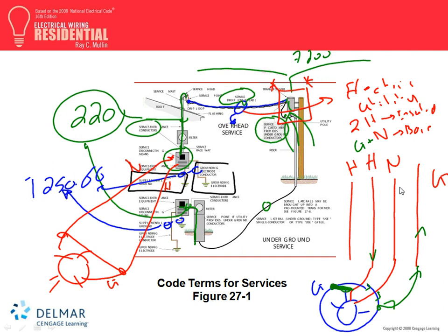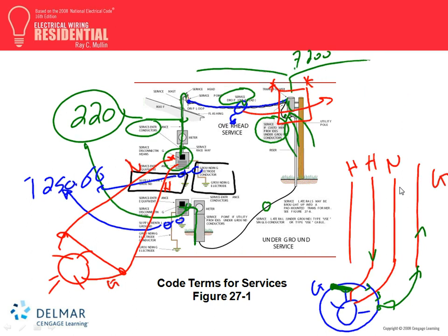It has to go to the source, guys. It has to go to the source ahead of it. How is it going to go to the source? Because right here is where my transformer is. My transformer is sitting right in here. Here's my hot, here's my other hot, here's my neutral. And now this current is going to go to the neutral. How would this current go to the transformer unless you bond? That's why they bond. So what do they do?